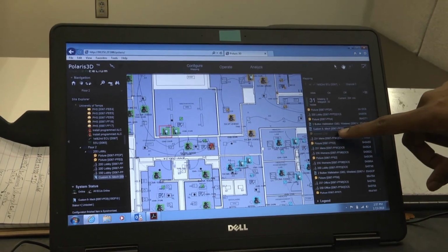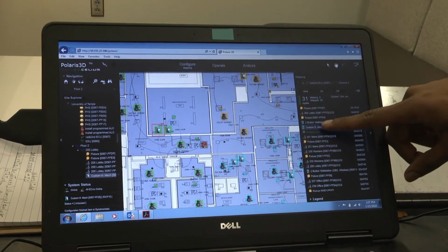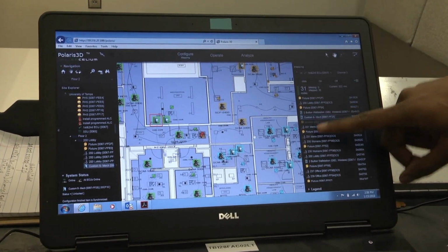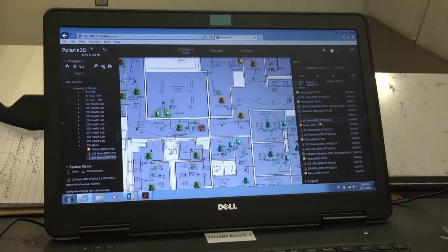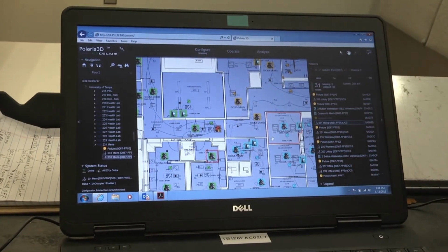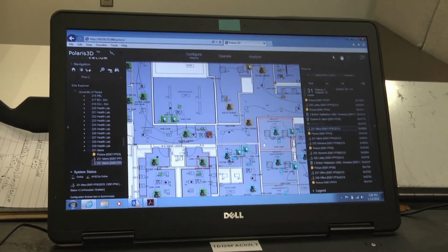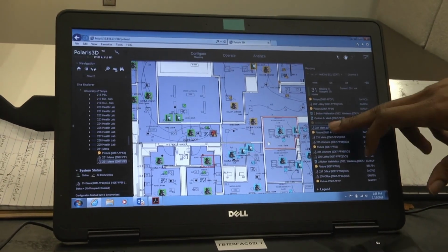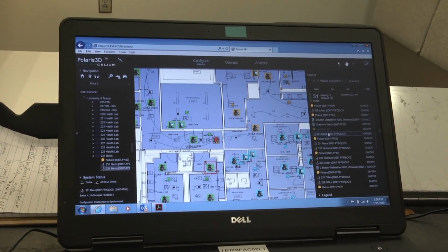So this module that's here, that's not programmed, it's somewhere in that vicinity because it's between that switch and this aux sensor. And here, so it's somewhere in this region, maybe in the corridor. We don't know until we get there. So we got to go up there also and do the same thing. Trigger the devices, select the device, wink it, see what happens, and then we program it. Okay. Cool? All right.